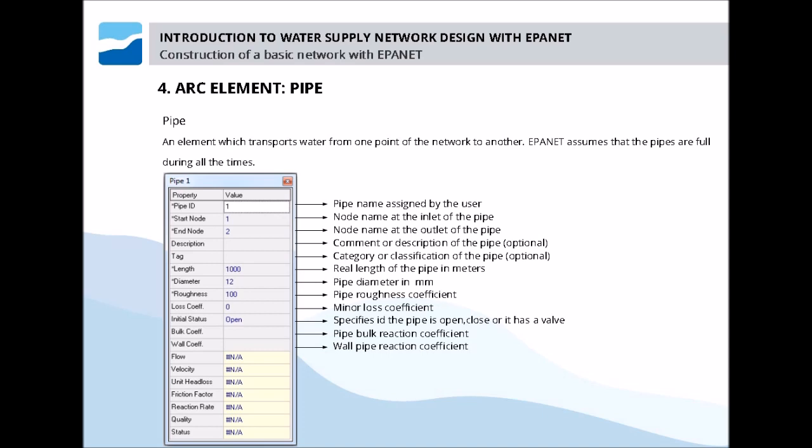once more, the name we assign to each element, the node name at the inlet and outlet of the pipe, inlet and outlet from a graphic point of view. We have already mentioned and shown that water will always flow from the highest pressurized node to the lowest one. These nodes can of course be different, depending on the simulation and on the demands.